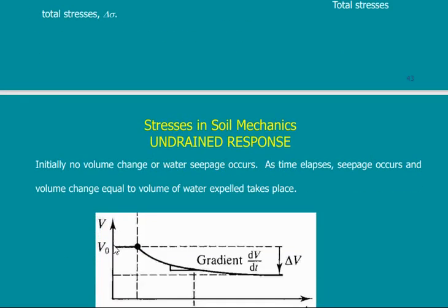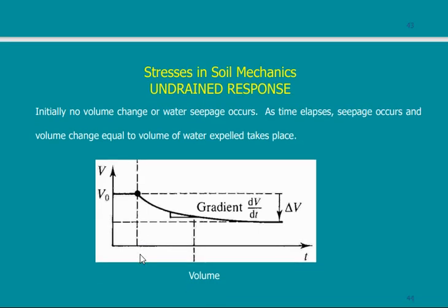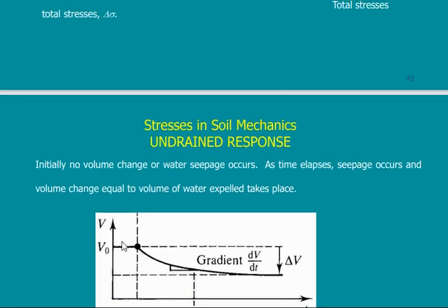So with the first portion of my graph, the volume is not going to change. Why? Because the voids are full of water, and the water is not free to leave. It is not like I just push a button and water leaves. No, it will take a lot of time. From here to there, the volume will stay constant.